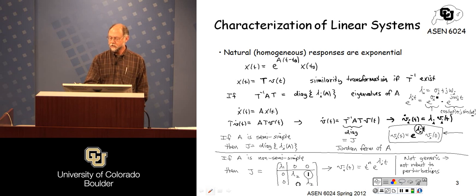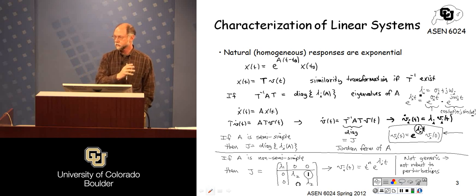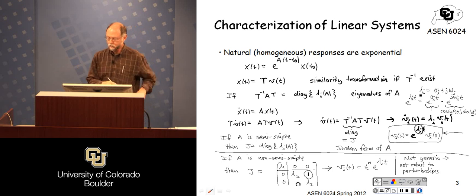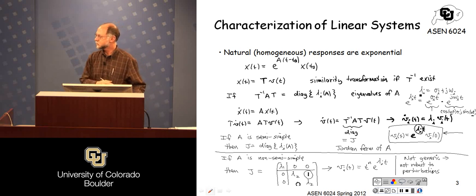The question then is, how do we change the eigenvalues from what we started with to what we want? And that control design problem really comes down to choosing eigenvalues with your control design. Okay? And there are a bunch of techniques that we've already seen for how to do that. So it's a pretty straightforward approach to understand what the system is, what I want it to be, and how to get from one to the other. How to control the system to behave as desired.